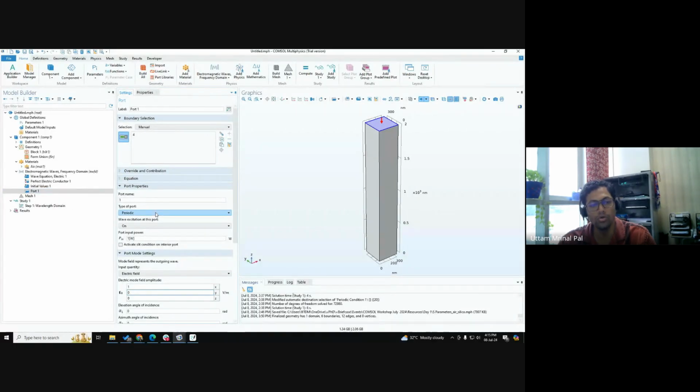How do you launch it? There are multiple ways. Basically, in optics you will either be working with periodic or with numeric ports. Periodic is the simplest way to start modeling. You just apply periodic boundary conditions at the ends, and you say it's a slab kind of thing, and it is very easy to model with. You put in any obstruction and you will get very good results, just assuming that the obstruction you place in the center is repeating on all sides.